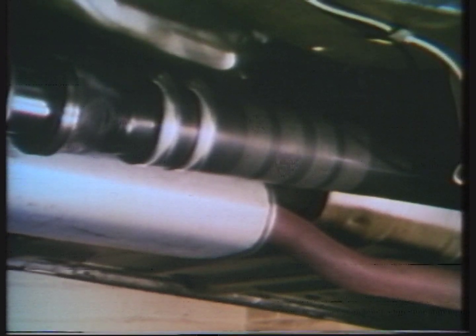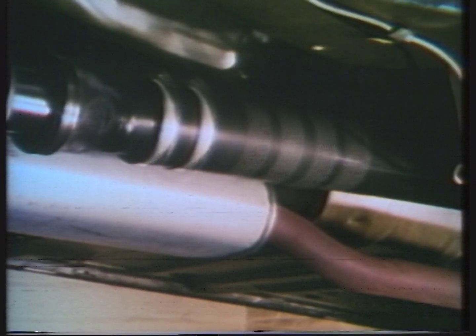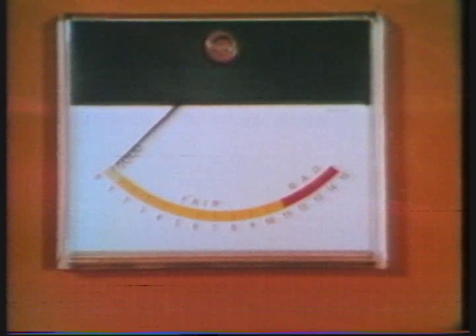And the balancing procedure is then repeated. If the unbalance has increased, the bottom clip should be moved to a comparable position clockwise. Repeat the operation, always moving the same clip in small increments until perfect balance is obtained.